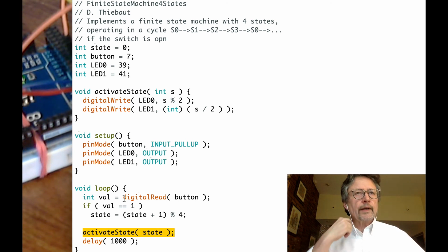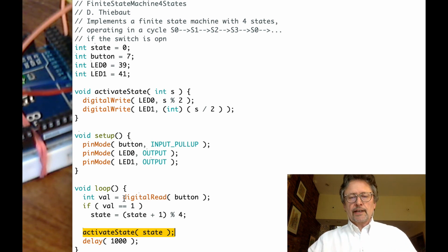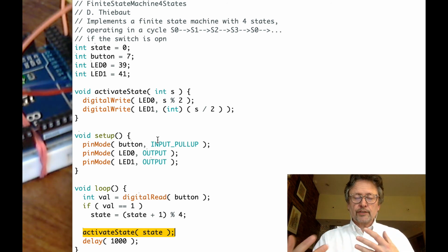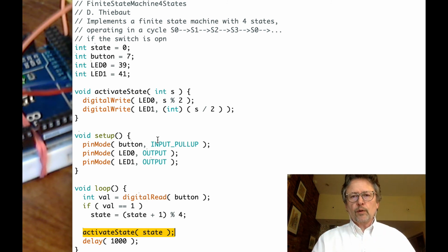So what if I want to make a change to my finite state machine? You see that with the flip-flop implementation, it's very costly. I have to change the equations, I have to remove the hardware, change wires. It's a very lengthy process. The software version of this, I just have to change the program. So the program is just kind of a version of the hardware. So the two, there's interconnection. I can switch from one to the other. Very flexible thing. The logic is the same, the implementation is different.